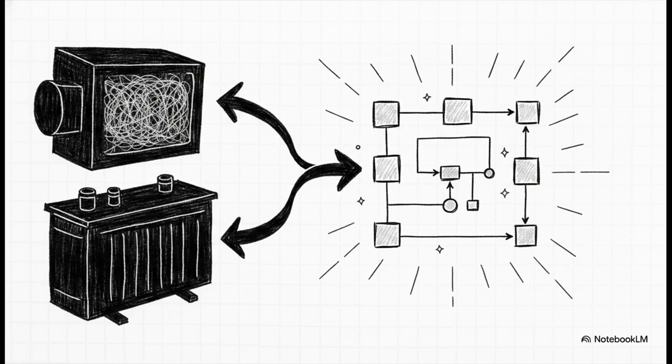And there you have it. You came into this pair of explainers treating generators and transformers as these mysterious, intimidating black boxes. But now you can model a generator's time-dependent reactances and a transformer's series impedance and shunt admittance. You know they're extracted through precise short circuit and open circuit testing. You even know how to navigate three-winding and tap-changing variants. The black boxes are officially conquered, and you have the mathematically sound equivalent circuits to prove it.